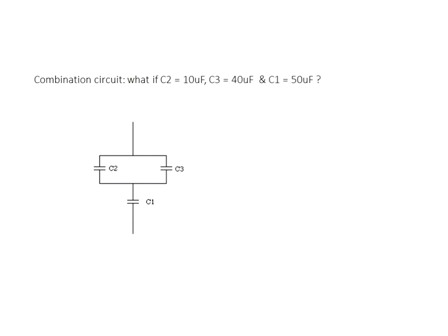Now, every once in a while on the CET exam, I've been seeing this problem come up. It could be flipped over, it could be pictured as it is. They'll give you two capacitors in parallel, which you'll have to find first. Simply add them together. And this becomes one big capacitor, which is in series with this. So what is the value of C2? C2 is 10 microfarad. What is the value of C3? C3 is 40. So 40 plus 10 would be 50.